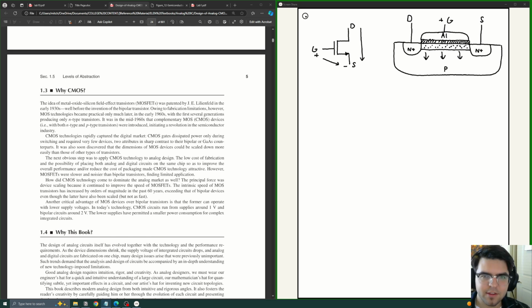These qualities, combined with the fact that they're great at switching, make MOSFETs strictly better than BJTs for digital designs. For analog, I don't think MOSFETs perform as well as BJT devices, but because they can be made so cheap and scaled so small, those are also pretty desirable qualities for analog design. So that's the trade-off that we'll take.